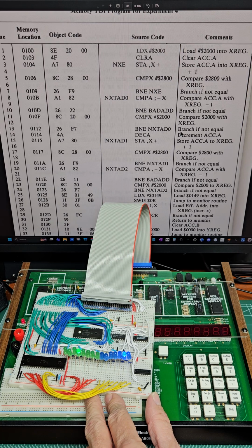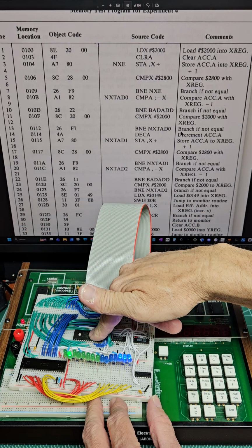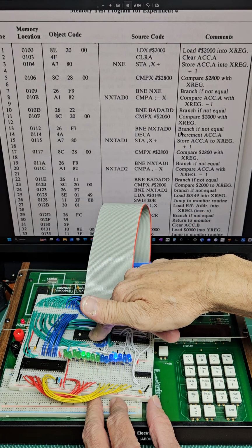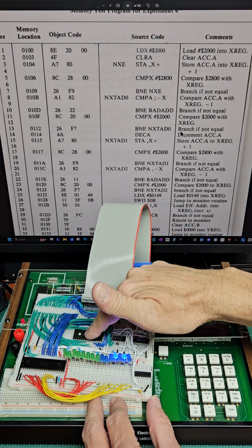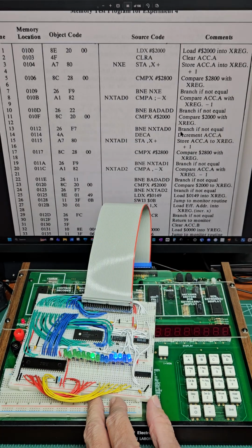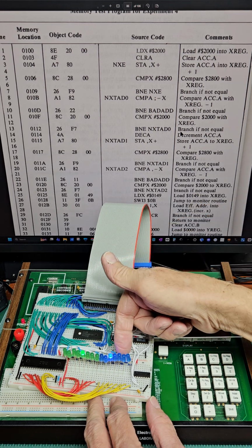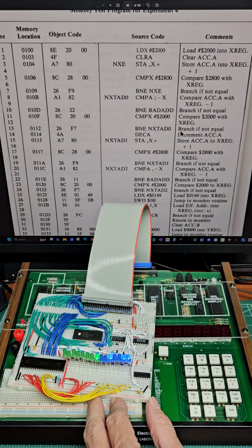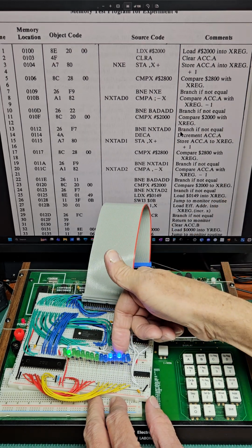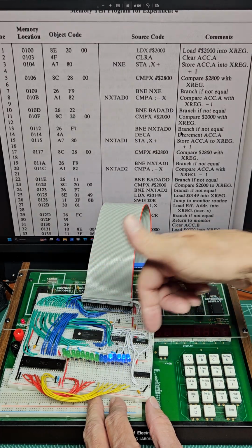And there you go. So right now, the processor is reading the commands on this EEPROM, and those commands are telling the processor to control this PIA device. You see, it's continually counting binary up to FF on the 8 bits on the right, and then 8 bits on the left. It's just going to rotate to the right.